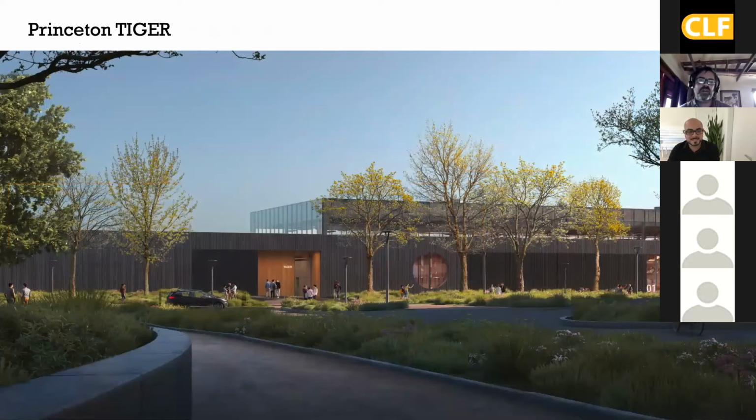One of those East Coast projects is at Princeton. They're expanding their campus with a new central utility plant, which is pretty exciting. It's going to be zero fossil fuel, using thermal balance and a ground source heat pump to supply this new campus. There are a lot of heavy athletic facilities, but other elements too. As part of that, we are using this process and working with a local supplier to identify a mix that has fly ash, slag, and Portland limestone cement for an optimized reduction in concrete carbon.